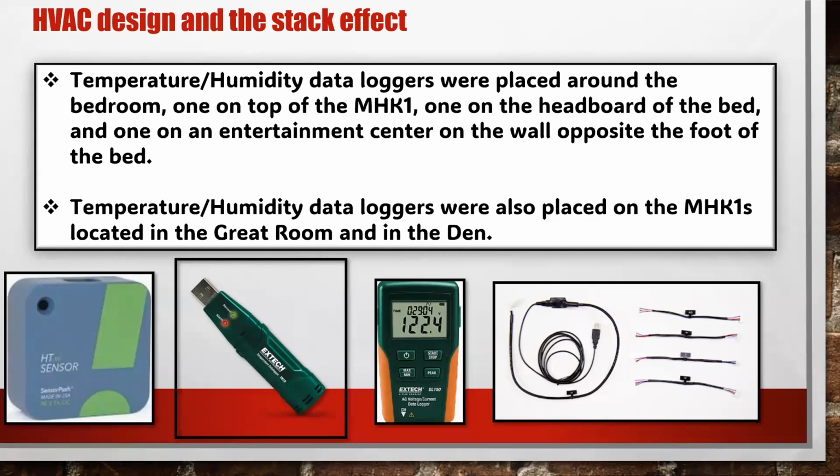And so we're going to taper some MDF or something and try to make it look nice, but not everybody's a carpenter, and there should be some kind of trim kit for those ceilings. Not to mention there's 2x4 framing and nothing to hang off of the rafters, so we have to sister 2x12s and then make a bracket to hang it. But it's all that stuff you learn when you're doing it. The trim kit would be nice for those, or something to make up for that.